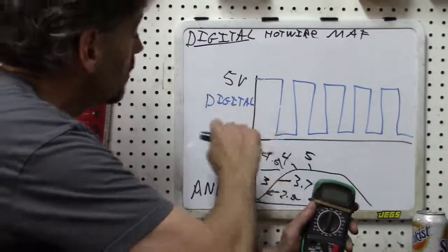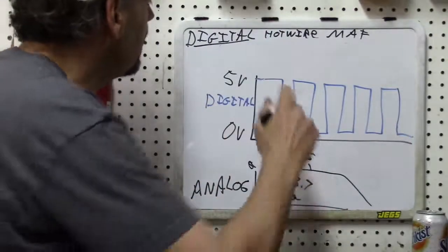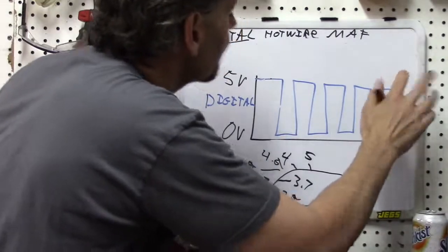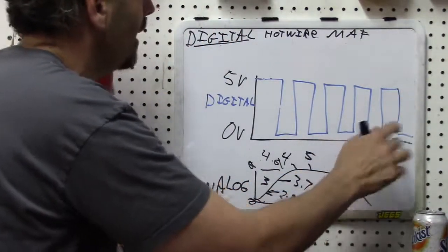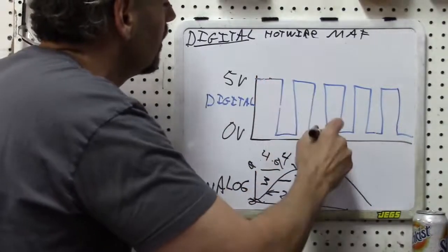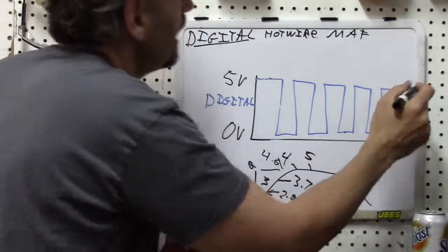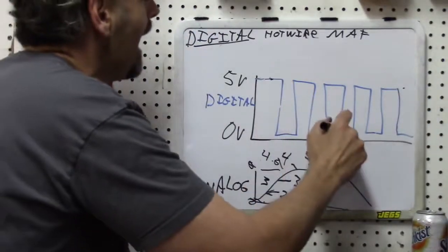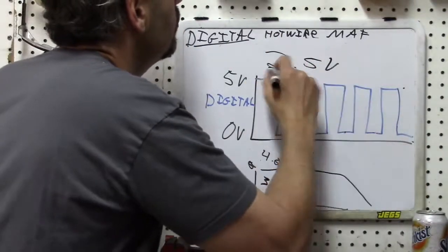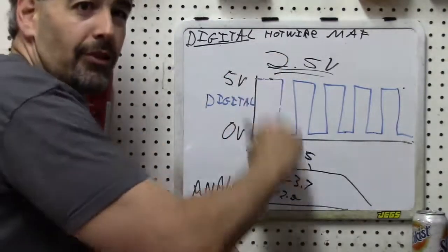You're not going to see that on a digital signal, because your slow meter is going to be taking readings only every so often. Actually it would be, remember, there's thousands of these. So let's have a reading here, and then way down the line we get another reading up here. The problem is when it averages your readings, it is going to show 2.5 volts. It is not going to show 0 and 5, 0 and 5, 0 and 5.